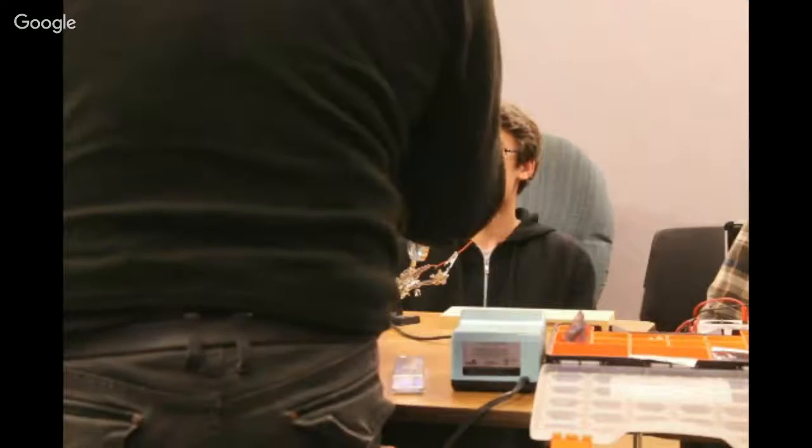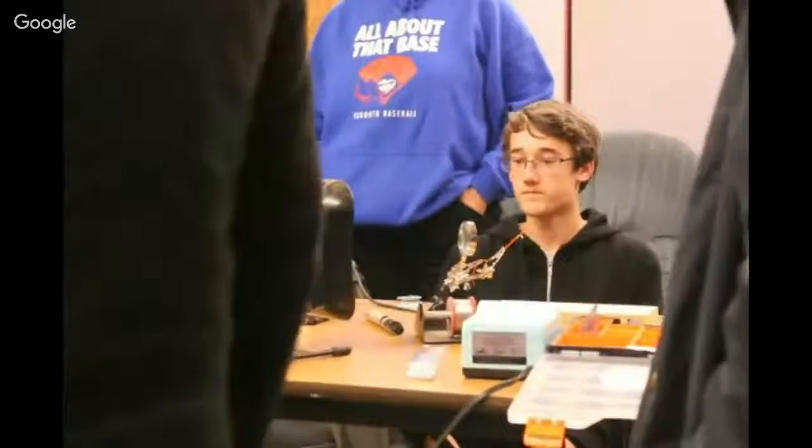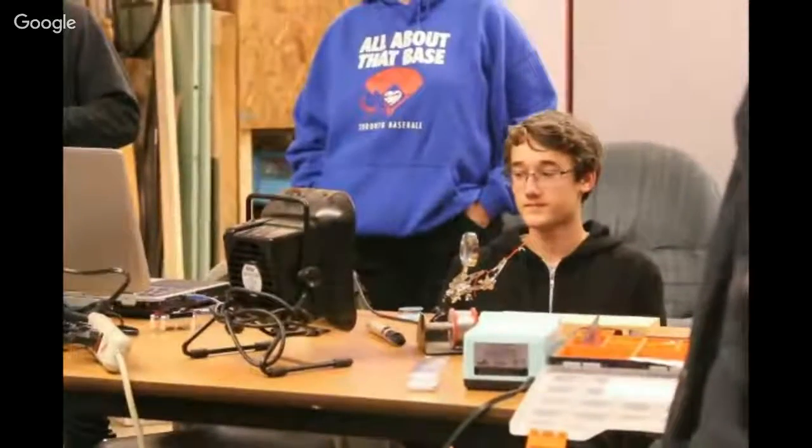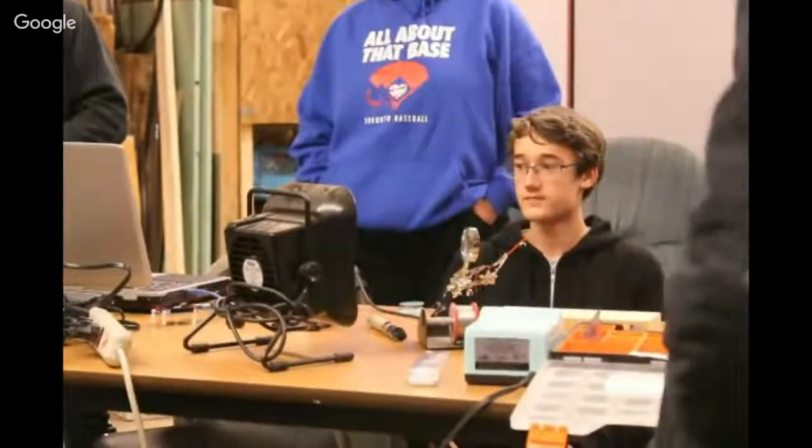It does not say it's a rosin core solder. It's also a lead solder, which Barrett's been talking about a little bit. Well, exactly, and that's what this is for. I don't use them very religiously, and probably I should, but the charcoal fan will pull the organic vapors and leads and everything out of the air, so it is a good thing to use.